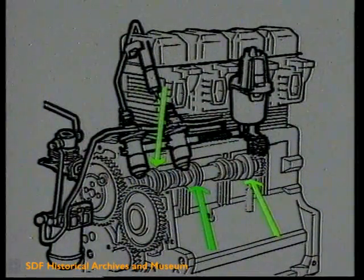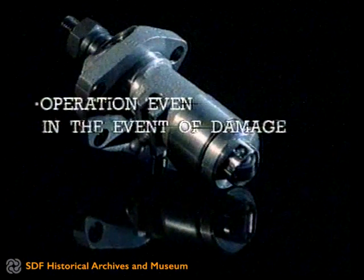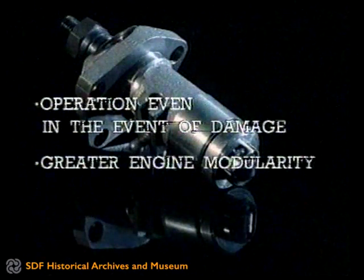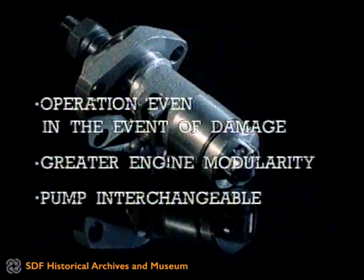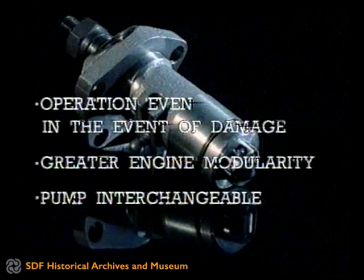To the characteristic advantages of the immersed pump can be added the possibility of operating the engine even in the event of damage to one pump, greater engine modularity, thus modifying servicing costs and time. The same pump is interchangeable on all engines of the same family, reduction in the stock of parts.